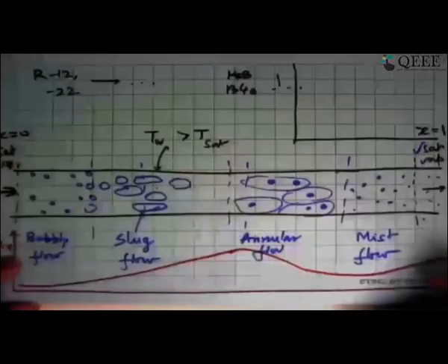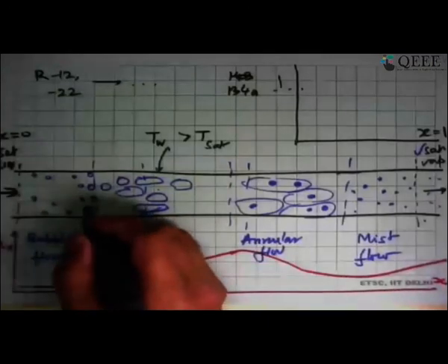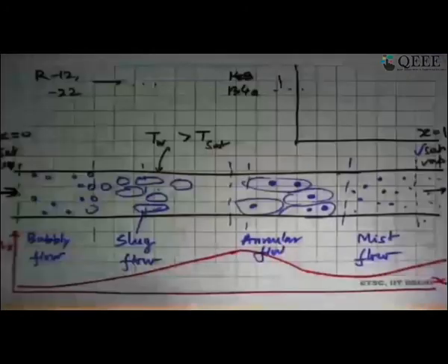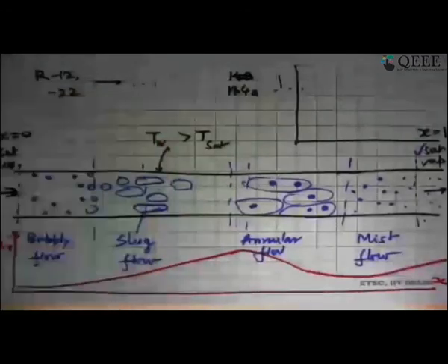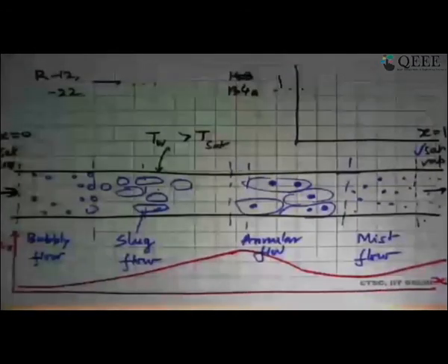Okay, so this is the role that surface tension is playing in the boiling process. The same thing is happening over here. How many of these bubbles will form depends on the surface tension of the fluid, how these will form and how they will join is also governed by the surface tension. And we saw that in the correlations, surface tension comes into many of these relations. So that's the thing.